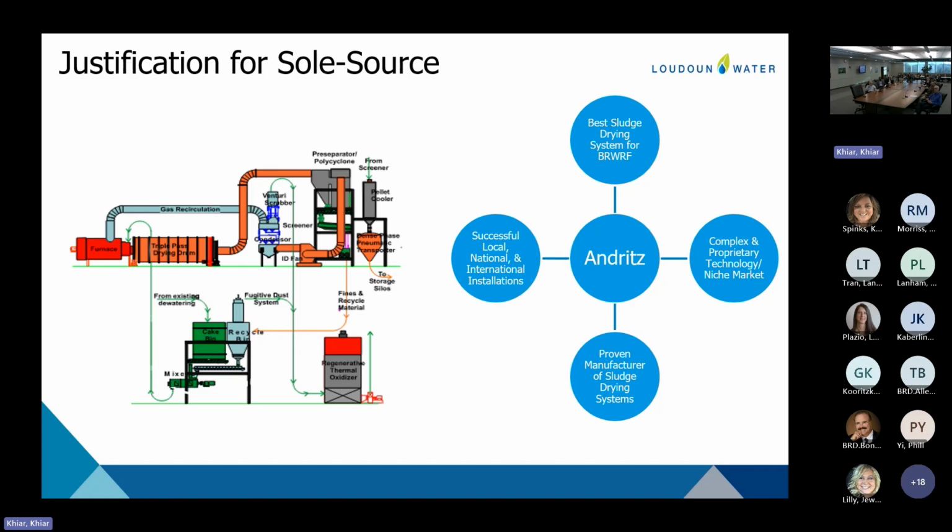Optimal size pellets go to a pellet cooler and then go to a pneumatic transporter that conveys the pellets to storage silos. The undersized pellets are returned to the recycle bin. Those are the nuclei or the core that form the new pellets. And then the oversized pellets go to right here. There's a crusher that crushes the oversized pellets, making them into smaller components that also go to the recycle bin and serve as, again, the nuclei or the core of the forming pellets.